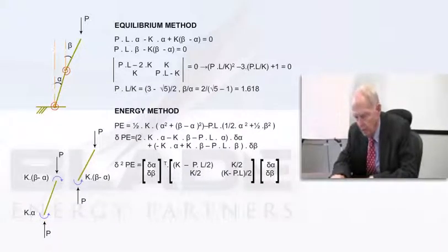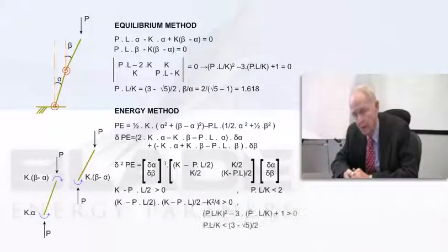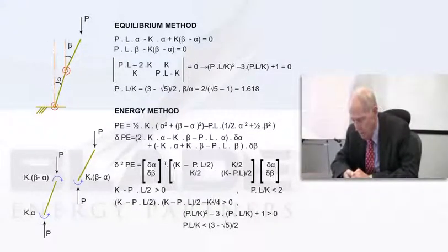Then you step down, you do the 2 by 2 in the upper left-hand corner, and you calculate the determinant, and that's the second discriminant. And in this case, that's all there is. So you write down your two discriminants, and they must both be greater than 0, or you don't have a stable system.